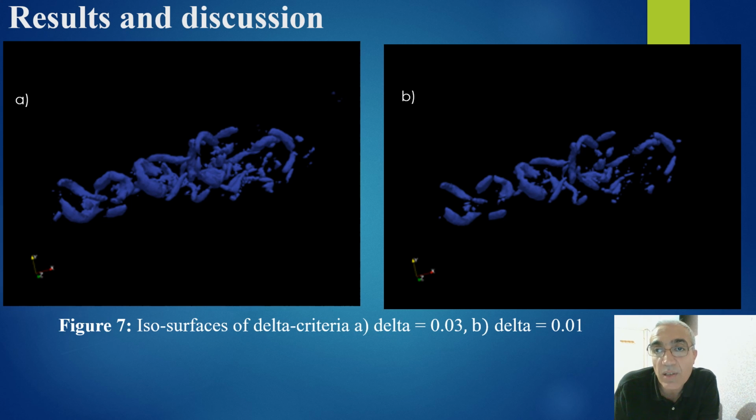However, if we adjust the threshold as shown in figures 5a, 6a, and 7a, we can clearly see the main and the secondary vortex structures, and it is also seen that these structures are well stable. From figures 5, 6, and 7, the problem is to choose the right threshold for the three criteria that we use to capture the vortex structure in the process. It is sometimes difficult to choose an appropriate threshold for the lambda 2, Q, and delta methods. The choice of the threshold relies on the correct identification of the primary and the secondary eddy structures. Figures 5b, 6b, and 7b give a poor representation of the vortex.